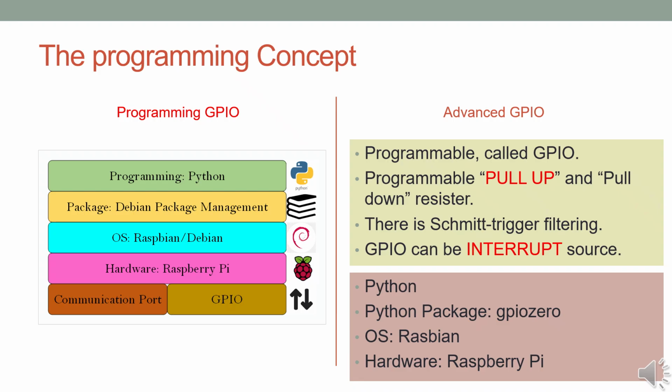This abstraction is powerful. Rather than thinking of pin 4 as a generic input, gpiozero lets us think of it as a button. This shift in terminology not only makes the code more intuitive, but also reflects real-world usage. For instance, push buttons are typically monitored not just for their high or low state, but for changes in state when a button is pressed or released. These transitions are known as edge events, e.g., rising or falling edge. Handling such transitions manually, especially when dealing with interrupts, can be difficult for new developers. With gpiozero, much of this is handled internally.